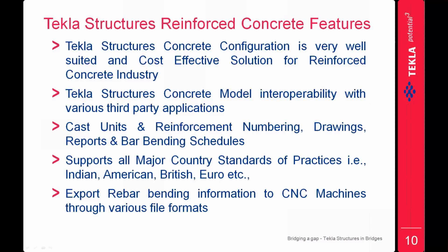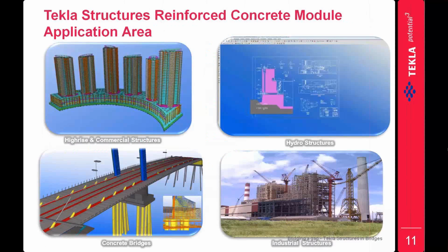And it supports nearly 33 country environments. I mean, the 33 country standards of practice, like Indian, American, British, Euro, and by default, with the installation, you are going to get 33 country environments. And even we can export the rebar bending information to the machines through various file formats, so that we can automate the whole process. And the Tekla Structures reinforced concrete module can be used in different areas, starting from high-rise commercial structures, and hydro structures, and even bridge structures and industrial structures. But today we are going to discuss more on the bridge side.